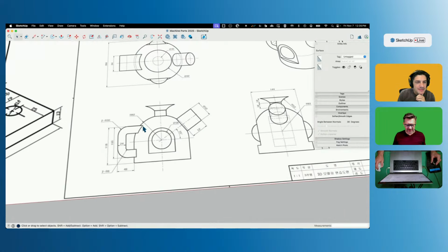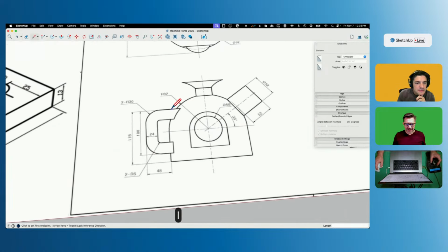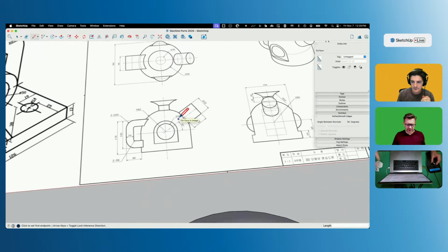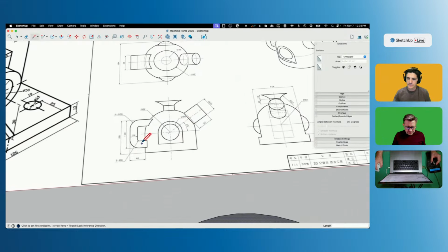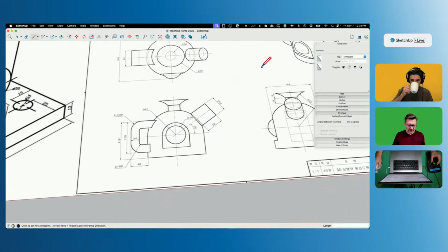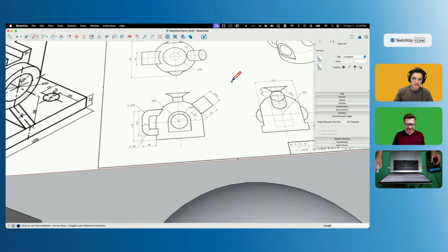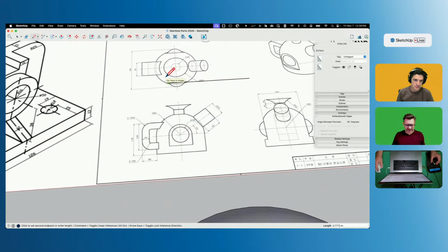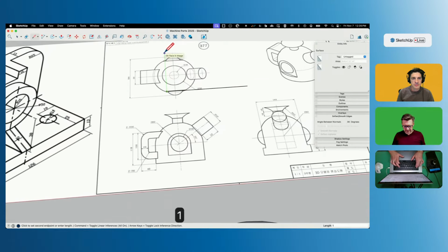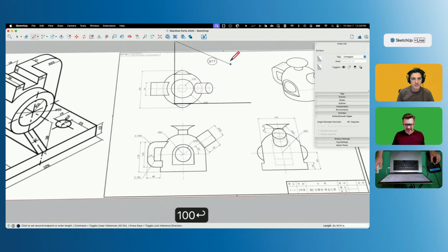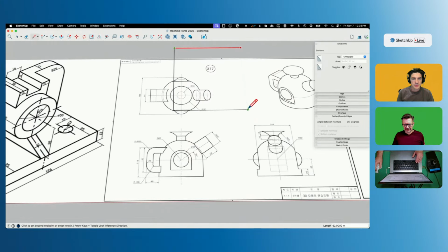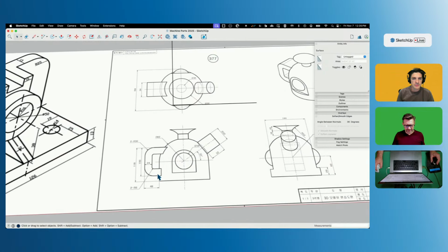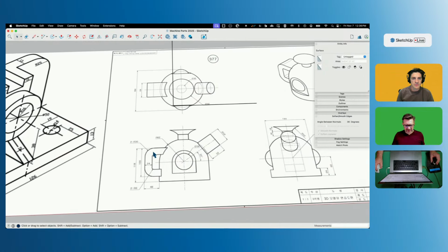Good stuff. All right, I'm going to model this handle on the ground and then bring it in and intersect it. So if I start right here, this is some amount, right? It comes out 48 from the edge, but I'm just going to draw something like this. And then it comes up 100. And then I'm just going to take it back in like this. So I'm just getting the outside of the shape right here is what I'm really looking for. This is a radius of 30.